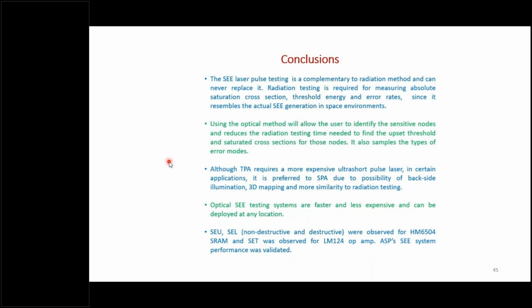And finally, SEU, SEL, non-destructive and destructive, were observed for HM6504 SRAM, and SET was observed for LM124 op-amp. And as I said, these were already verified in the literature. We use these just to validate our laser system. So we did validate our laser system performance by observing these SCE effects.